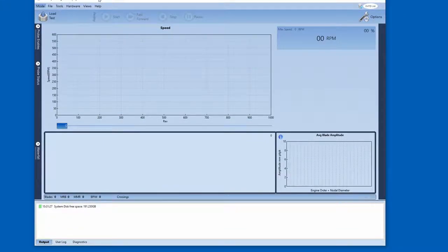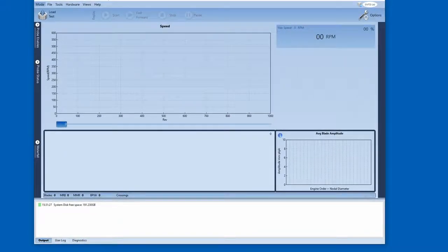And I'm going to do it in replay because the alarms work just as well in replay as they do in acquisition, and it gives you the ability to test the alarms to make sure they do what you want, or rather they do what you think they should do. Okay, so it's perfectly valid to do it in replay. The only alarm that's not valid in replay is the stack alarm, but that's because there's no stack on display in replay in real time as there is in the acquisition.